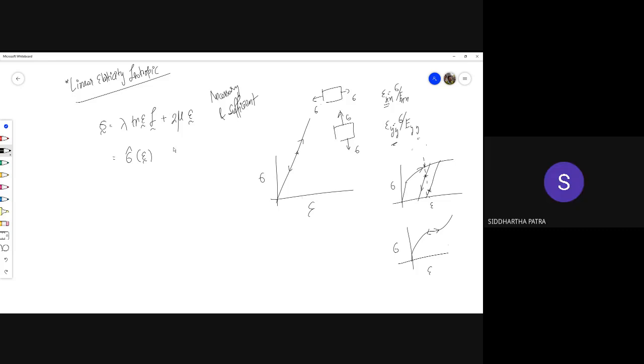Okay. The third thing is isotropy, and let me try this. This is how you rotate a strain tensor. Earlier, you were applying certain strain in x direction and certain strain in y direction. Now you have rotated it, so the strains are acting in 90-degree rotated directions.